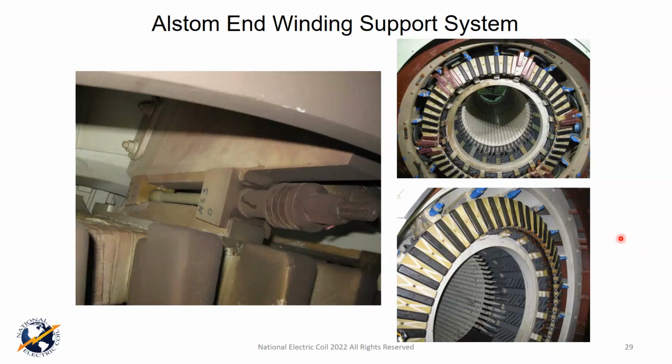Actually, there was a CIB released by Alstom in 2015 after a failure in Lancashire, UK. And then subsequently, there were TILs from Ansaldo and GE to modify this phase break connection. The reasons they gave are improper bracing, workmanship issues, and that the amount of bracing in this joint is not adequate.